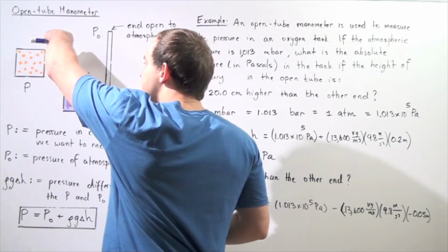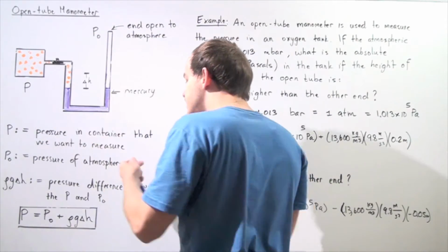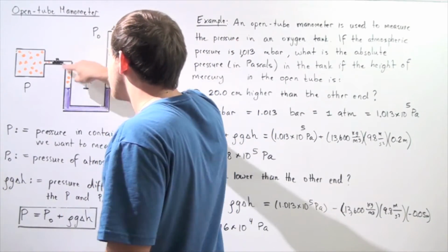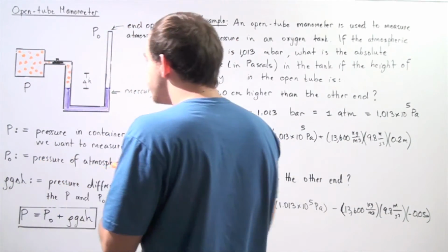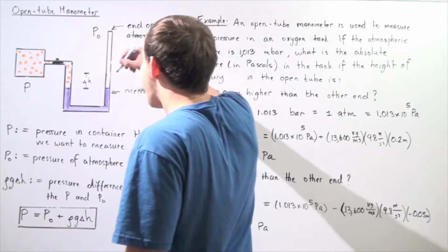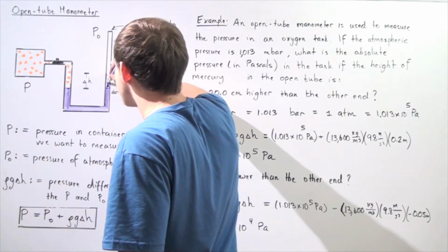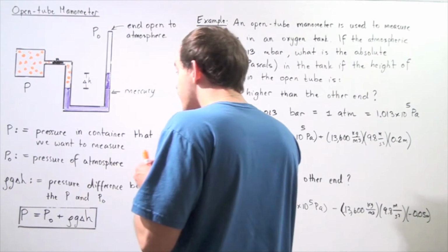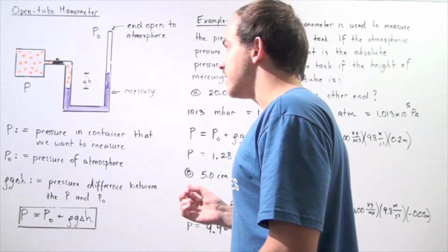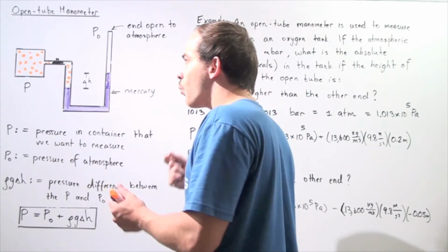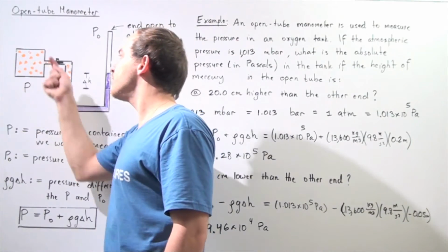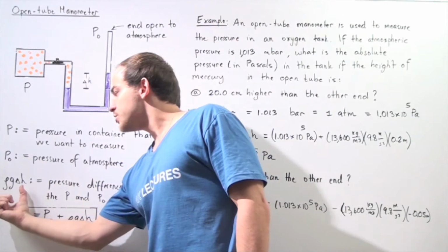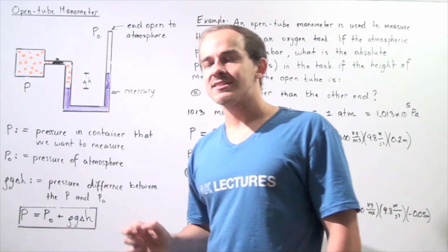And because the pressure is higher from this end than from this end, because we assume the pressure here is higher, that means the pressure due to these air molecules found in the container will push the mercury a certain distance, change in H. So let's suppose this change in H is given by this distance here. Now we can calculate, using the difference in pressure, what the actual pressure inside the container is. So we can calculate this difference by simply using our equation for constant density.